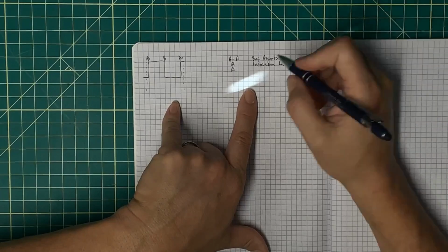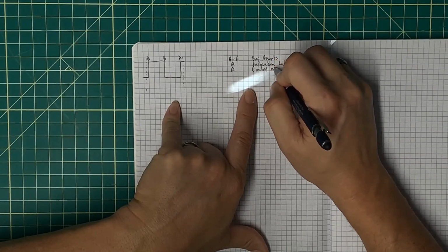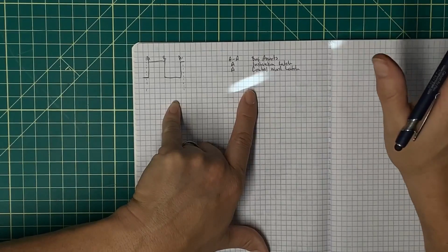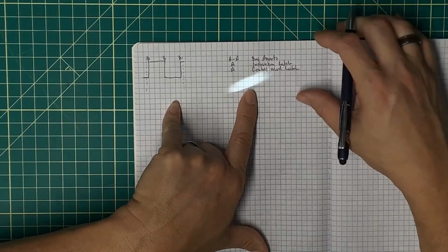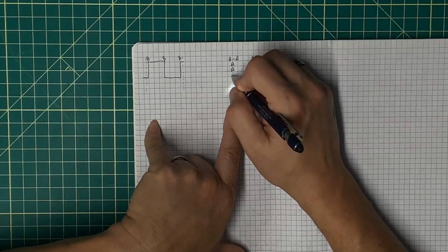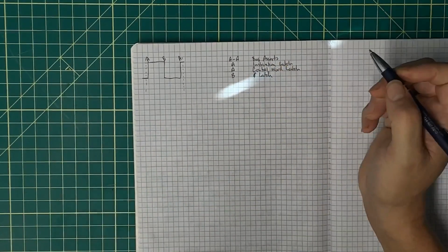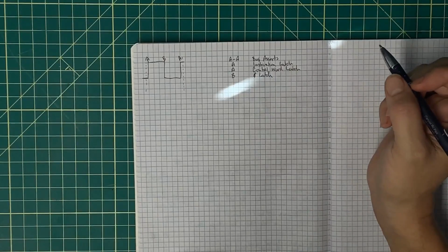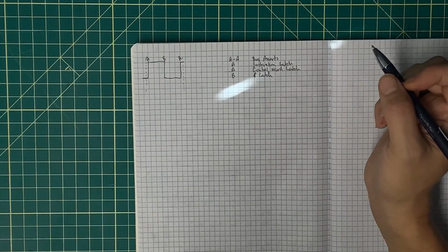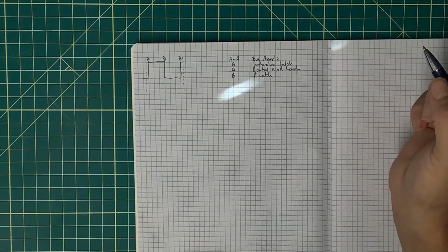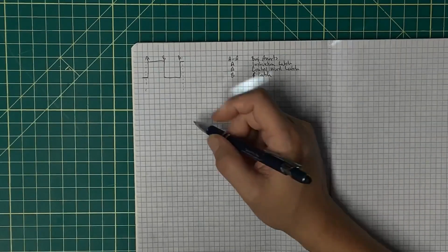At event A, I've also got my control word latch, and that is on the control ROMs. Those are the latches of the data coming off the EEPROMs. At event B, this falling edge, is where I am performing my AND latch. And that worked for me pretty darn good until I started having problems with jumps and loads and the like.